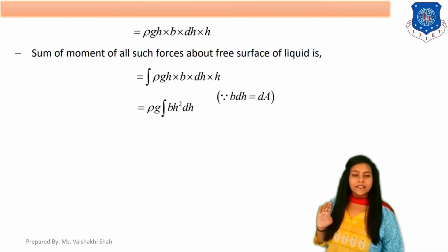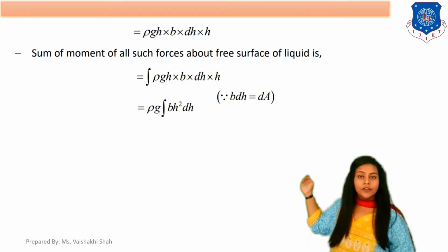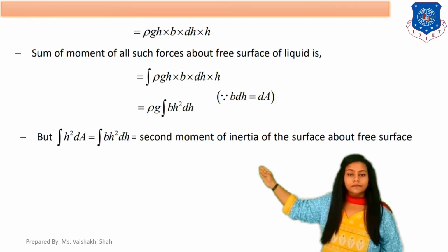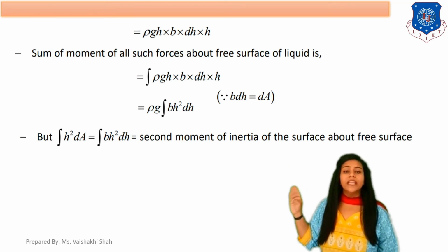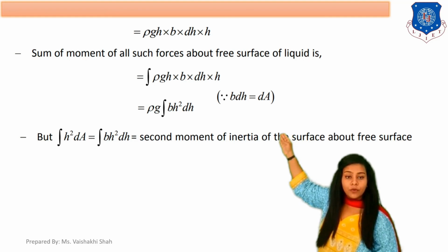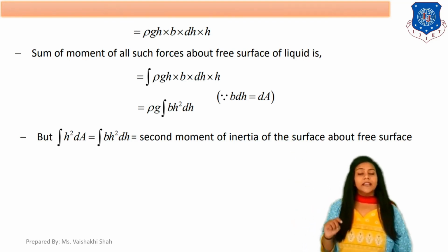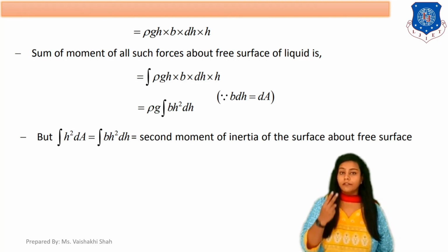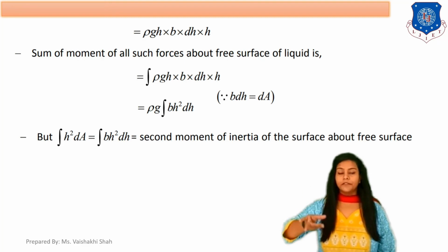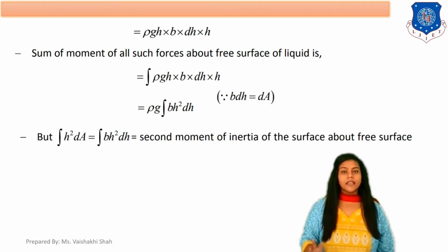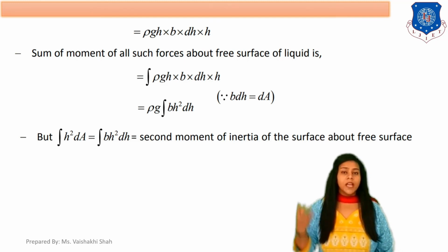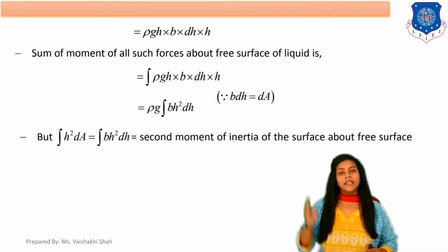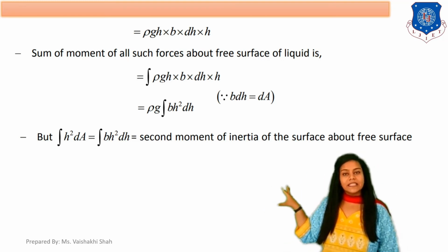So the next step is rho into g, which is constant, times the integration of h square into dA. Now the integration of h square into dA is the second moment of inertia about the free surface of the liquid. You will study the moment of inertia concept in your subject called mechanics of solids, and we apply that concept directly in your subject fluid mechanics and hydraulics.